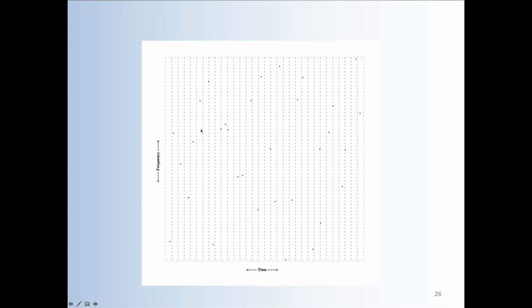So a signal of this type, this so-called location coding type, might look like the following. Each one of these dots represents a bundle of energy in time on the horizontal axis and frequency on the vertical axis. And each one of these dotted outlines contains 2 to the 11th possible locations for this bundle of energy, meaning that it communicates 11 bits of information. And only one of these locations is occupied by energy, so that specifies those 11 bits. So we have a sequence of these squares, each one having a bundle of energy in a different location in general. And over time then we're communicating a stream of bits.